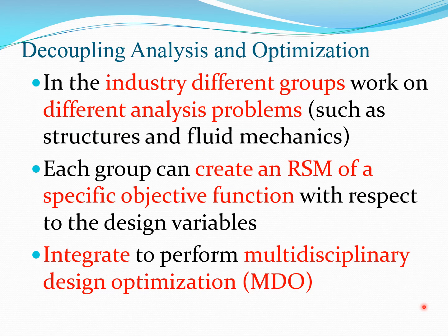So we can imagine a situation where there is a company, and maybe it's developing something such as a flight vehicle, in which case you may have different analysis groups: a structures group, a fluid mechanics group, and so on. Each group can develop a response surface for a specific cost function with respect to the design variable. And then there may be some people who have expertise in optimization who combine all these response surfaces and come up with an optimization problem which they can then solve.